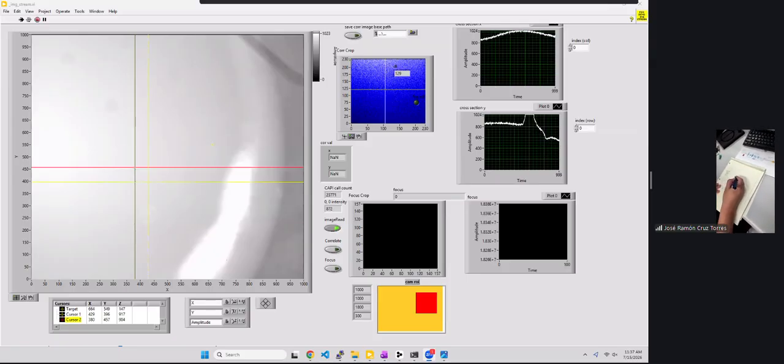In an ideal world, you would get a linear line that looks like this. But what actually ends up happening if you have backlash in your system is you get something like this, where this is a certain threshold. This is your x-axis intercept. If you give the motor any input command that's lower than this threshold value, it's just not going to move at all when you return it back, because it doesn't overcome the backlash at all.